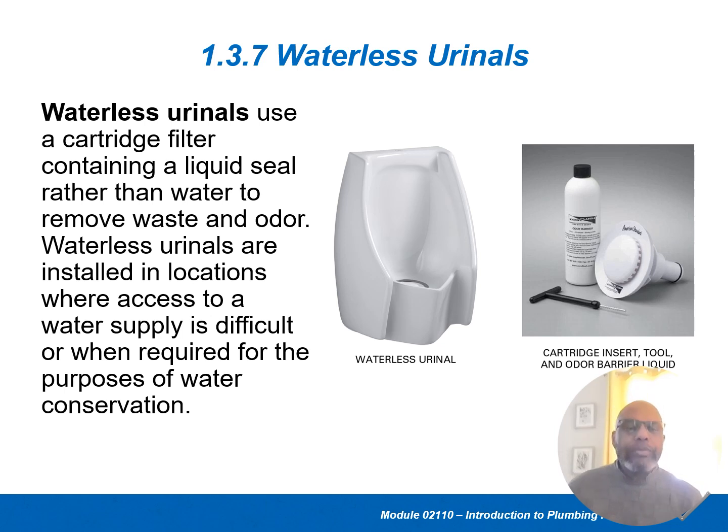Now, waterless urinals, it's a little bit different. It uses a cartridge filter containing a liquid seal rather than water to remove waste and odor. Waterless urinals are installed in locations where access to water supply is difficult or when required for purpose of water conservation. So where you find this is sometimes on the side of highways where you see rest stops. And so they could not get water there, or remote areas, so they may put one of these in. It would still go out a drain.